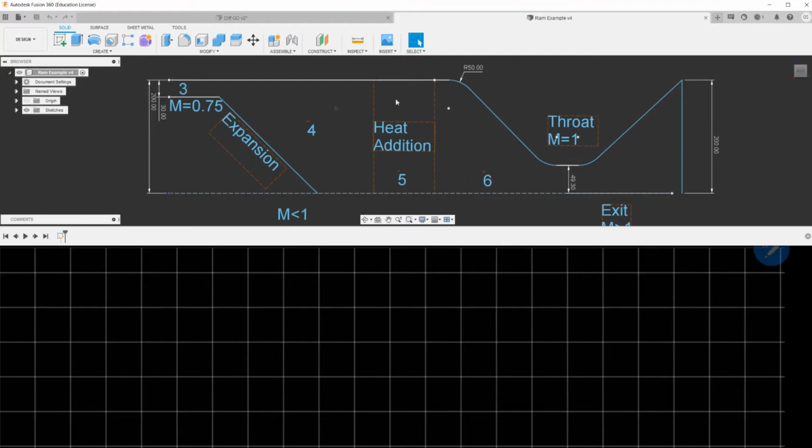And further, after heat addition, we calculate the nozzle. So the nozzle is a consequence of the results of the diffuser design. Right, so we do diffuser design, heat addition, and then the nozzle, all in line. So we have all parameters in a sort of system. It's a step-by-step calculation, but you understand that the parameters of the throat, the size of the throat, are strictly related to the shock waves you calculated before. So we're closing our system in this way,